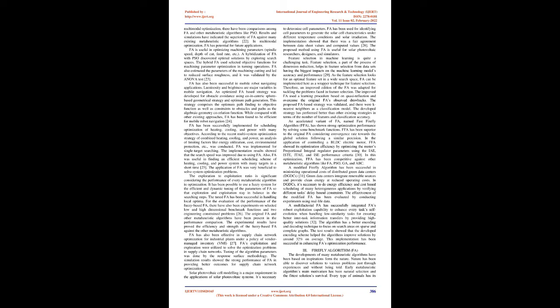FA is useful in optimizing machining parameters, spindle speed, depth of cut, feed rate, etc. A hybridization of FA with PSO discovered optimal solutions by exploring search spaces. The hybrid FA used selected objective functions for machining parameter optimization in turning operations. FA also estimated the parameters of the machining cutting and led to reduced surface roughness, and it was validated by the ANOVA test 23.